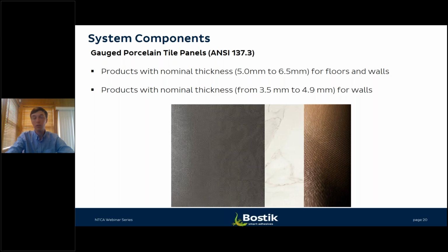If it's your first time especially, you want to ask about the techniques for cutting and fabrication, ask about the limitations, whether it's from a flexibility standpoint or a drilling standpoint or a use applicability standpoint. So get to know what brand you're working with. What are those product characteristics and how exactly can or do you need to work with them individually? So know your porcelain is a big key.